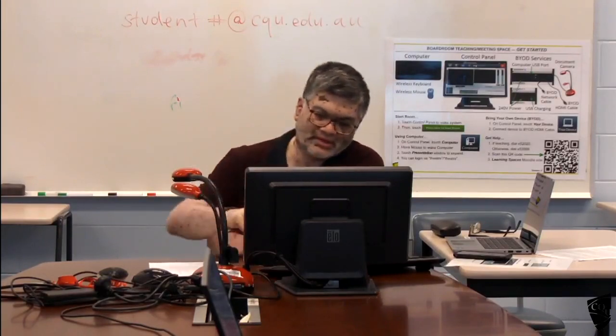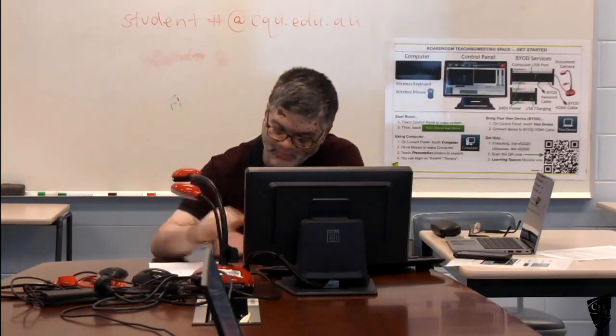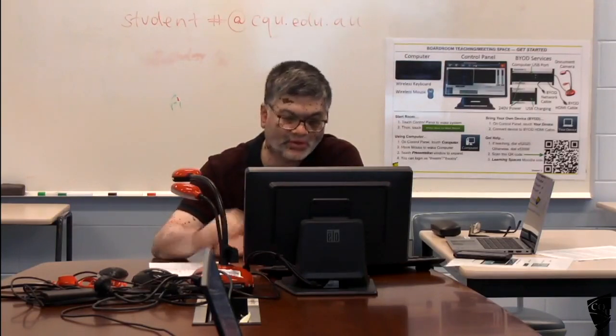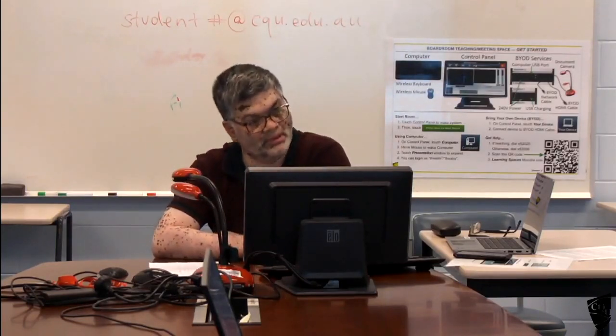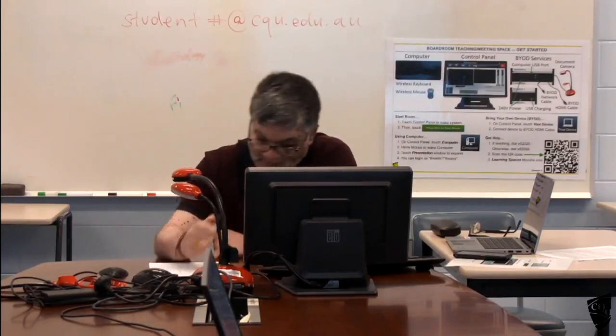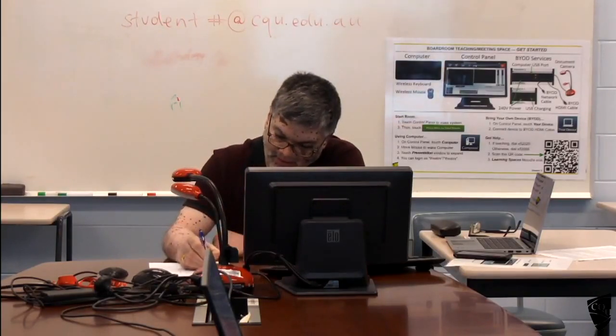So if you look at this panel, the load will go to the columns. Yeah, all the loads need to go to columns because there is no beams. Earlier, if you have beams, we said it will go here, here, here, here, but there is no beams now.